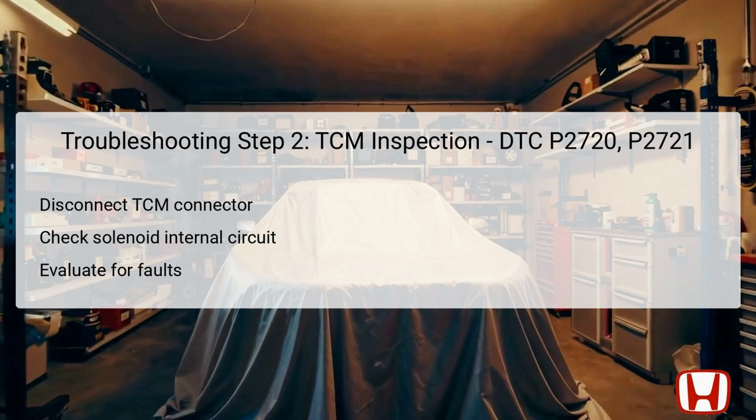Disconnect the TCM connector to begin this inspection process, making sure to jump the SCS line with the Honda Diagnostics System, HDS, beforehand to prevent any diagnostic errors. With the TCM disconnected, you will check the solenoid's internal circuit, which should display a resistance between 5.0 to 6.3 ohms to confirm proper functionality. If readings fall outside this range, it indicates a potential fault within the TCM itself, necessitating either repair or replacement.